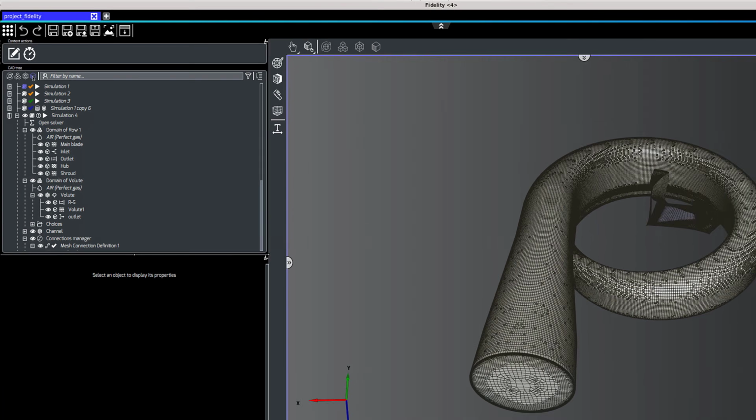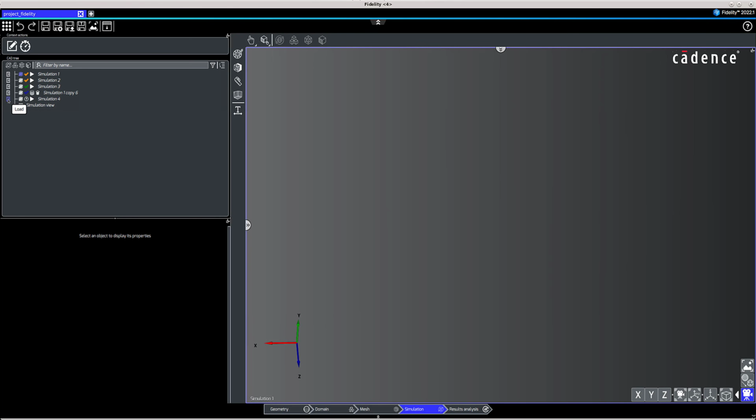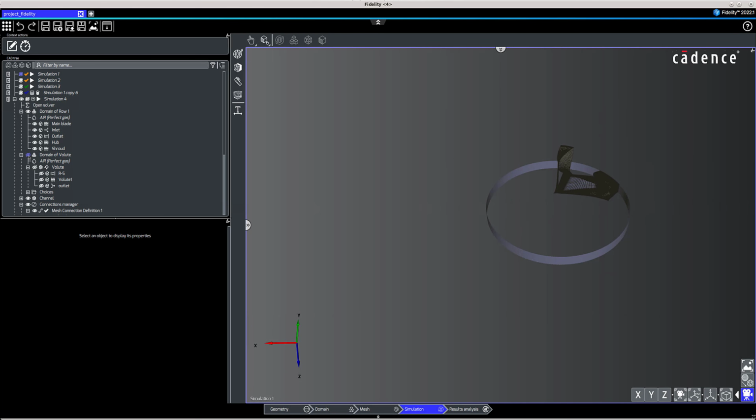Managing a big data tree can be time-consuming. In order to simplify the tree manipulations, different filters and actions can be used. First, let's review some of the main actions that can be applied on the tree. The door icon loads or unloads an item and its content in the project. The eye symbol shows or hides an item with a graphical representation.